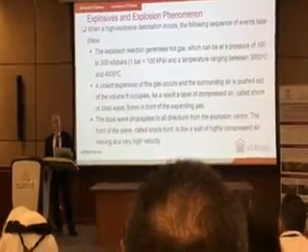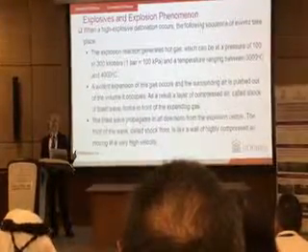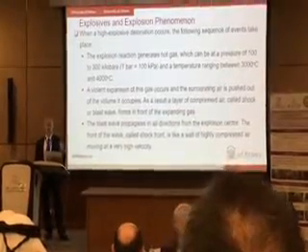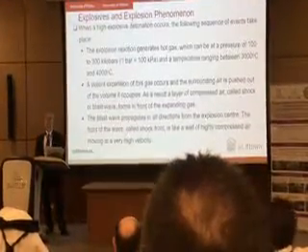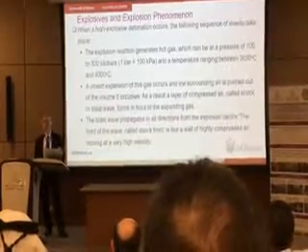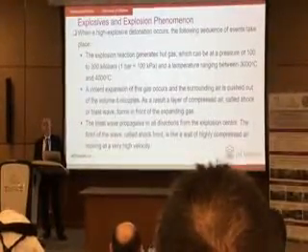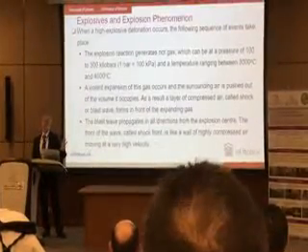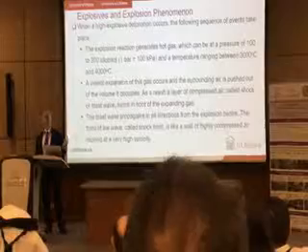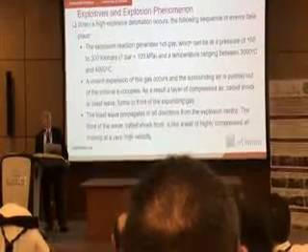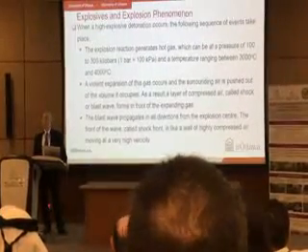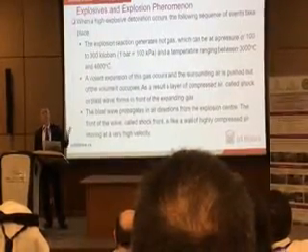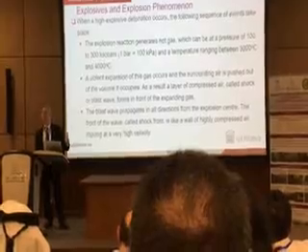When an explosion occurs, there's a tremendous increase in temperature and pressure. We're talking about 10,000 kilopascals. In our lab, when we go to 100 kilopascals, that is our limit for window testing. Most US and Canadian government agencies want protection against 100 kilopascals because that's the limit where a glazed window can sustain a blast.